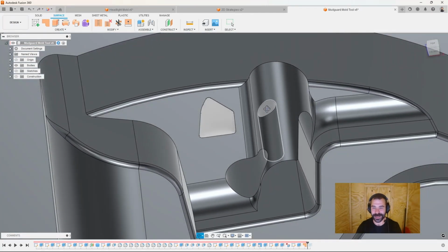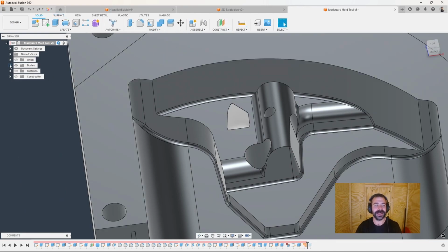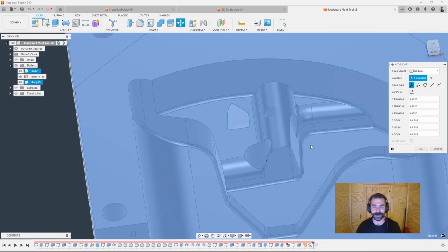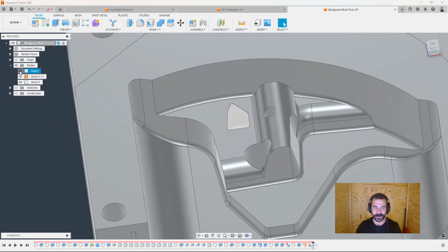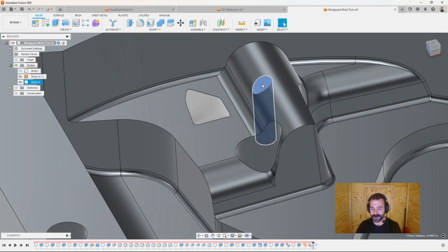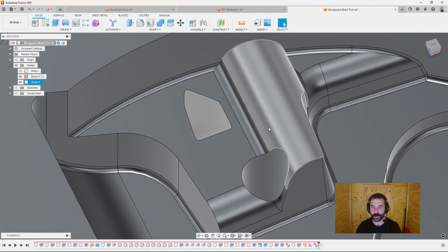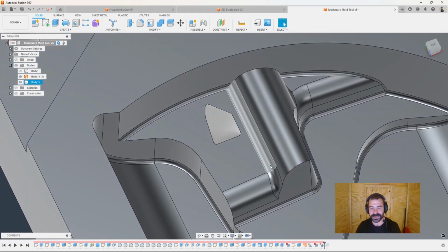The reason why we're crashing our model is because I made the mistake of being in the surface workspace. So we go back to solids. As a bad habit I'm certain to give you guys, and I shouldn't be, we need to duplicate that body with a little copy paste. Again, Control C, Control V, turn off that original, and then we can grab that surface. In this case, it's a blind hole, so we're going to grab it all the way down at the bottom. And again, we can do that right here with this hole too, where it's going to self-heal and patch itself up.